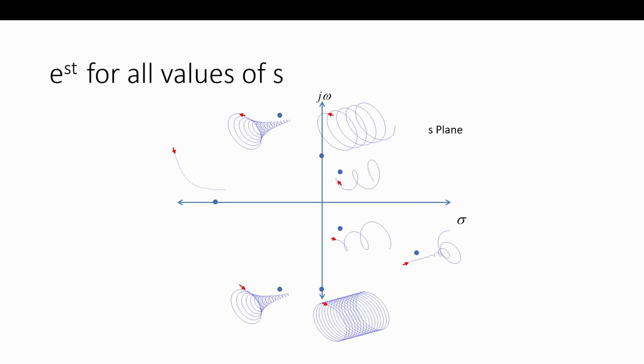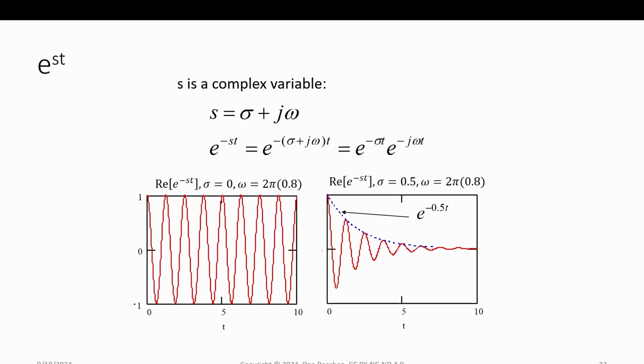You have some time domain function that's the filter. You give it an impulse and it kicks out. Okay, so what if that could be the impulse response of the filter right here? That's a low pass filter where I kick in an impulse and it coughs out that thing you're seeing on the right. This is a ripple decay. That's the impulse response. So if I asked, what's the Laplace transform of that, how would you describe this? How many components of e? It's already in that form, e to the minus 0.5t with the j omega, whatever j omega I use.